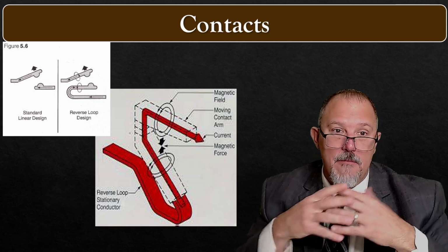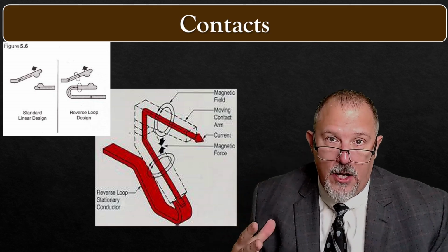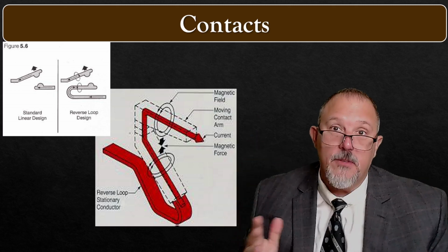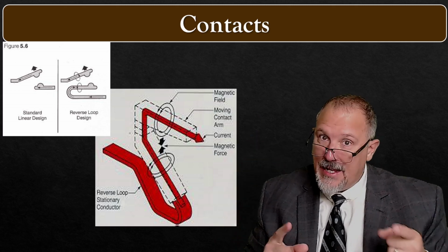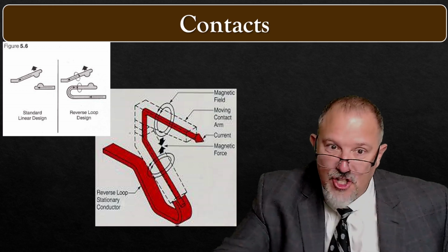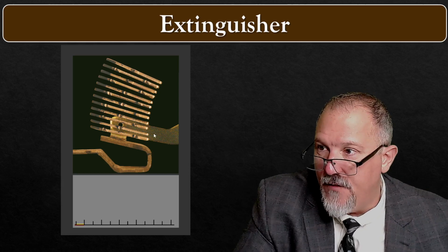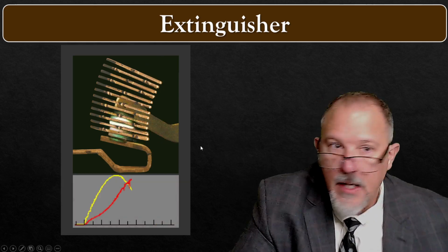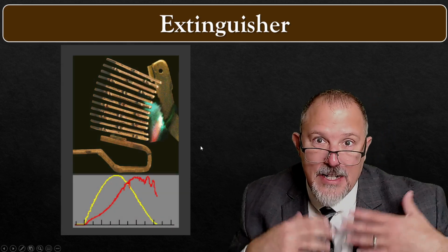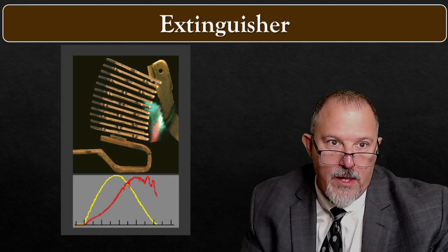And what am I doing? I'm leveraging the magnetic forces that we just saw in that video to blow these contacts apart. Like I said, the hardest part, holding them closed without chatter. The arc extinguisher's job and function in life is to divide and conquer that arc as it's drawing up in between the plates.